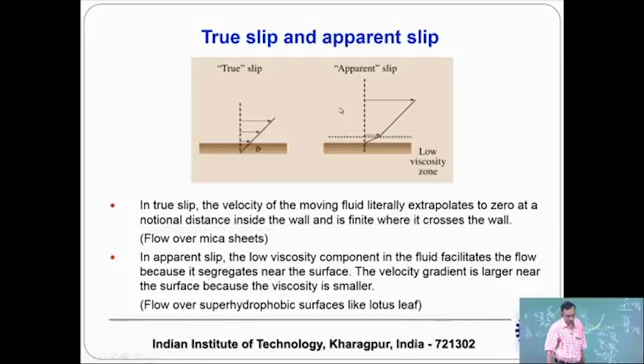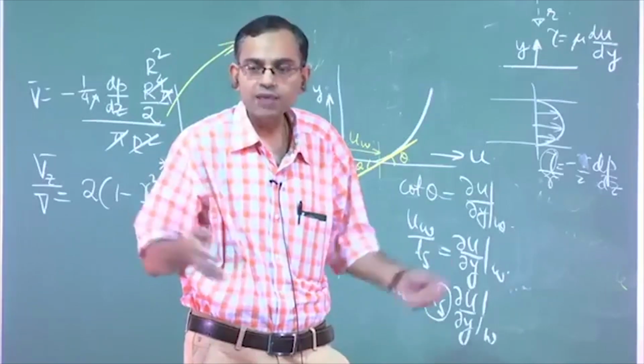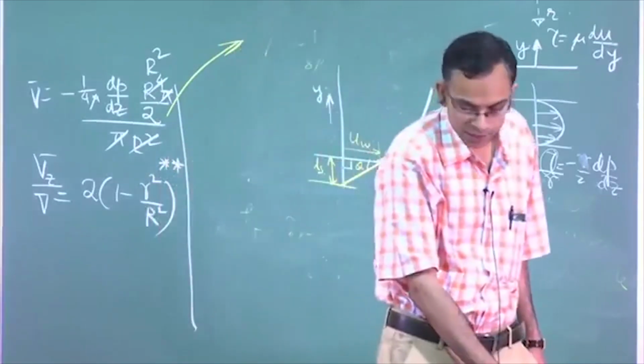So when the liquid is flowing on top of this wall, the liquid is not feeling the effect of the roughness of the wall directly. The nanobubble layer, which is shown up to this dotted line, will act like a cushion and the liquid will slide or glide over this cushion, that will make it as if it is slipping over the solid boundary.